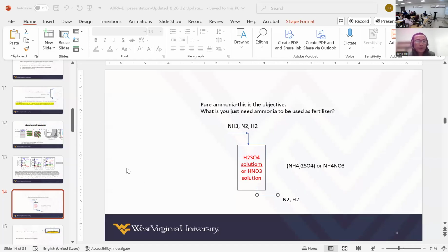So before we break, we talked about how, if you want the ammonia to be utilized as a fertilizer only, you can do that. It's very cheap. You do not need pressure swing adsorption. You do not need cryogenic. All you need is a sulfuric acid solution.